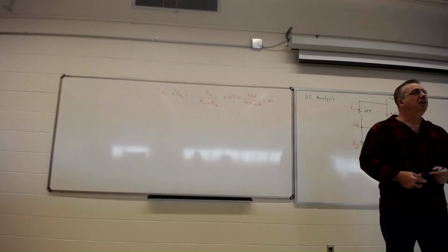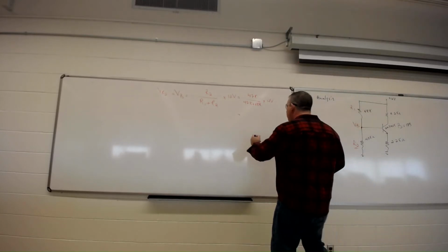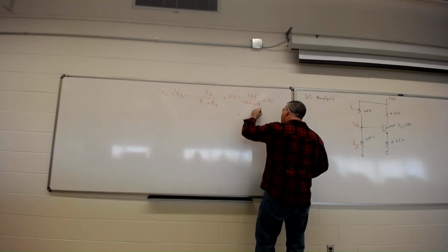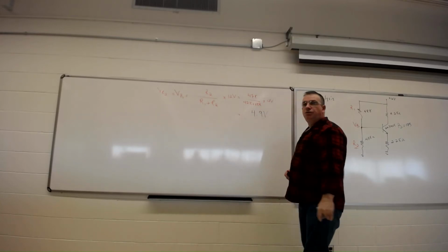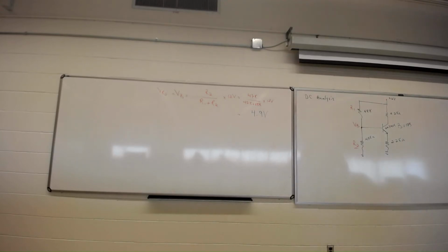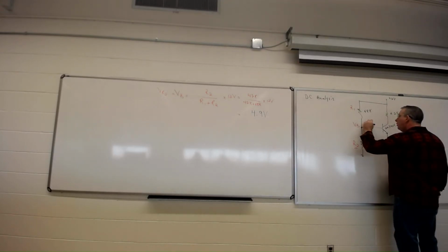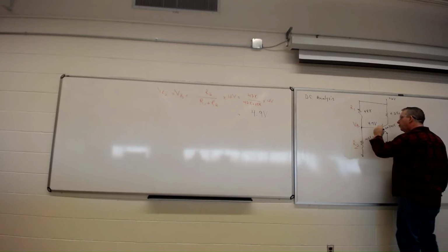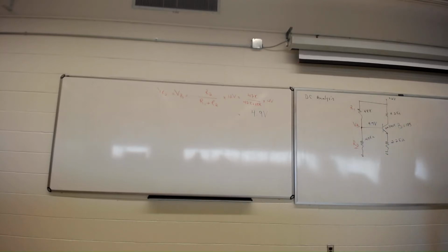Yeah, I'm getting 4.9. 4.9 volts is what you should get at the base. So right here, 4.9 volts at the base.